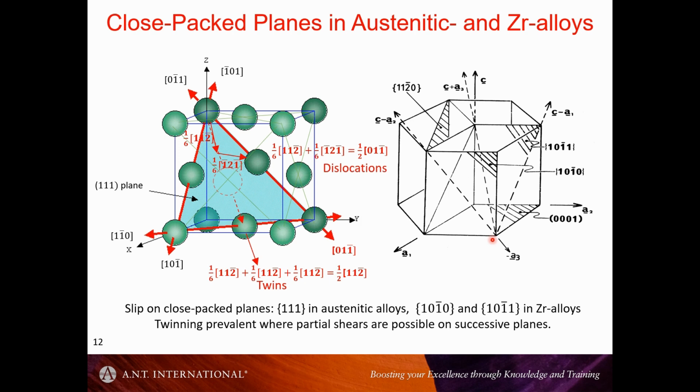And for comparison, we have the austenitic structure, which is face-centered cubic, and I stole this off the internet. This is a depiction of the atomic arrangement for an austenitic stainless steel, and the plane of interest is this one that goes from each of the three corners of the cube like this, and this is the most close packed plane.